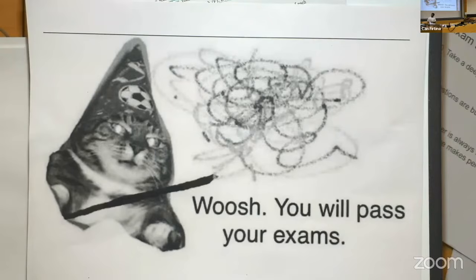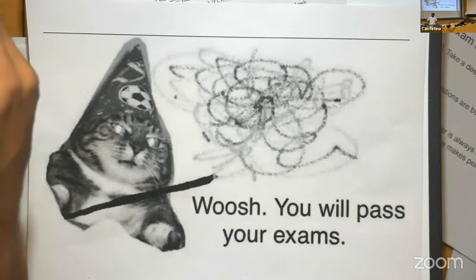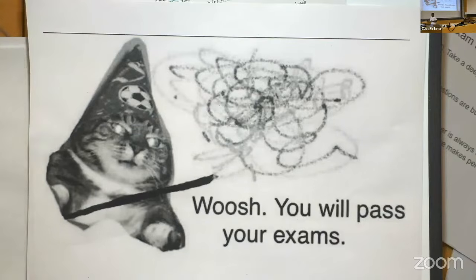It does not defeat it because your reservation station size might be limited. Yes, that is very much possible. So yes, you are absolutely right. You understand. So now I can see that you understand the concept of reservation station, because you need a large reservation station to extract the parallelism that gives you performance improvement in out-of-order execution. If your reservation station size is 1, then yeah, just do it scalar. Just do it in order. You're absolutely right.